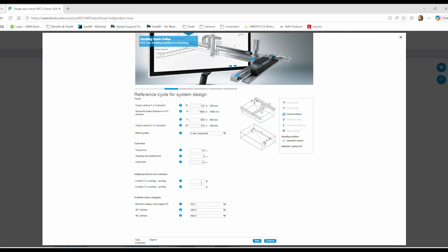So this is just saying if you have any positive or negative forces acting either with or against the movement, besides the payload, of the workpiece with the payload in hand, whether it's pulling it off of some sort of press fit fixture at the bottom and might have to overcome some force from there. That would be a negative force that's going with it, for example. For today though, we're just picking this off of a conveyor or just off of a table, so I'm just going to put 0 for both.